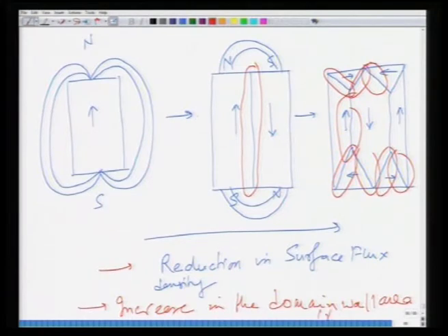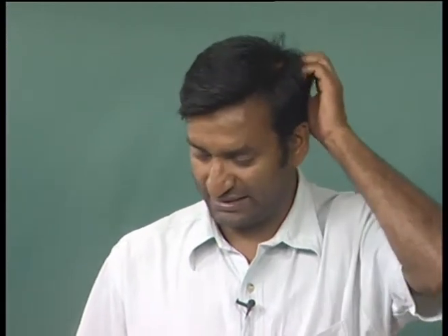So as a result, gamma, the typical term for surface energy, increases. So the stable domain configuration is one where the net free energy, which includes these two terms, adopts a minimum, and that would be the stable domain size. The analysis would follow a similar line to the analysis we did for ferroelectric material. Basically you have to differentiate that free energy term with respect to the domain size and find the stable domain size for a given combination of surface energy and surface flux density.